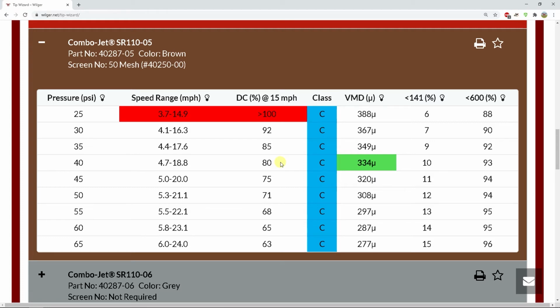60 to 80% is a good baseline. Not much penalty for going up or a little bit lower than that. But where you want to be free of is the trouble zones. So the trouble zones being at the low end of the duty cycle. Usually between 40 and 50% is not really a good place to be. Anything below 40%, and you definitely don't want to be there.